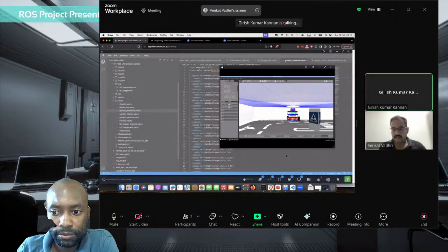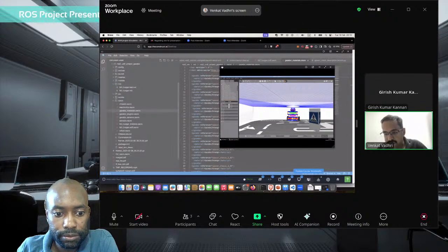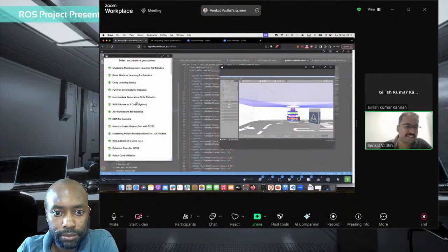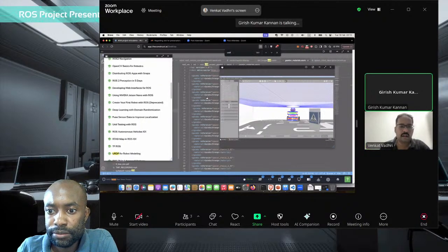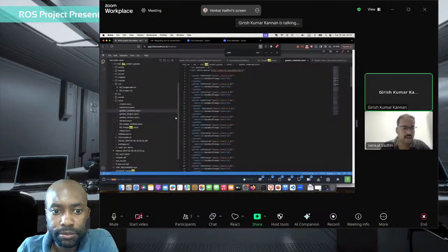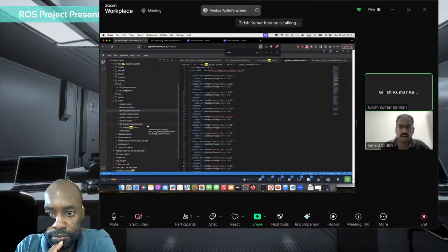Yes, I need that command. One second. No, you have the controller launch file written there, right? Just start that file, which will start the robot state, the joint state broadcaster, along with the two other controllers to spin the lidar.